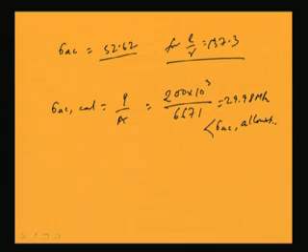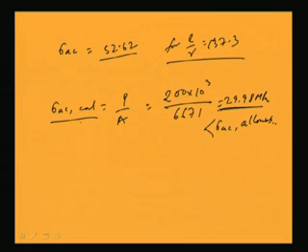So if we increase the sectional dimension to ISMB 350, then we are getting the section okay from compressive stress point of view, because the developed value is coming 29.98, whereas allowable stress is coming 52.62. So it is okay. Now I have to find out sigma BC.